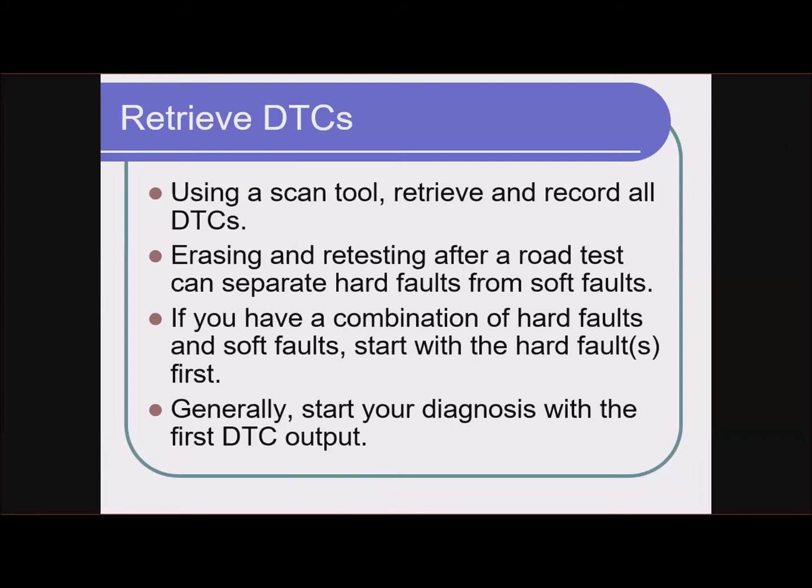So I could have just taken it to the dealer, but I wanted to see what the code was for. So I just put a scan tool on it and looked. And the code was for coolant temperature sensor. So obviously I didn't fix it, since it was under warranty, but I knew what they were going to find when they plugged it in at the dealership. And so it went to the dealership. They obviously found the coolant temperature sensor code and they replaced the coolant temperature sensor.